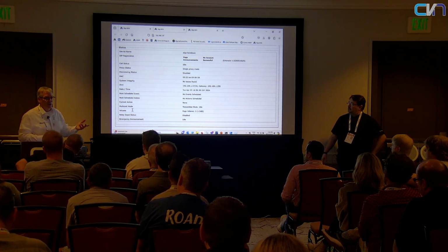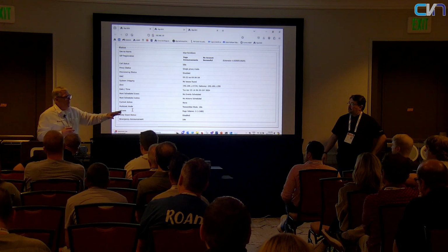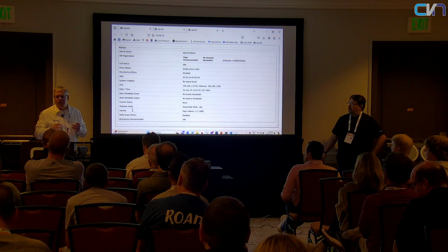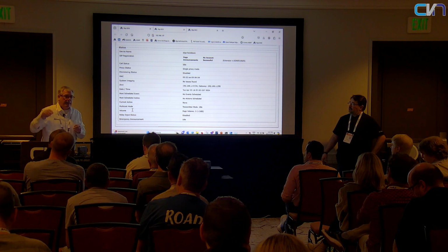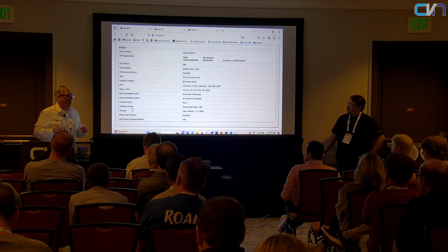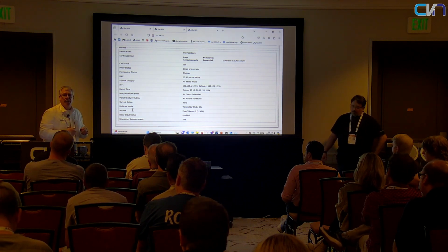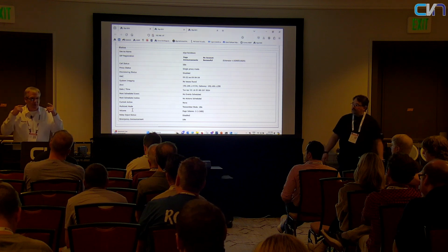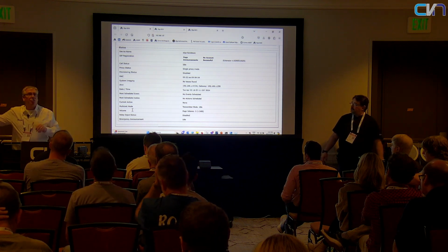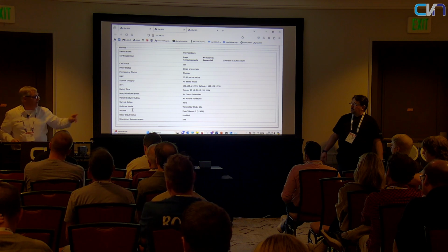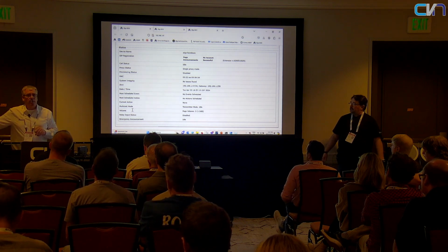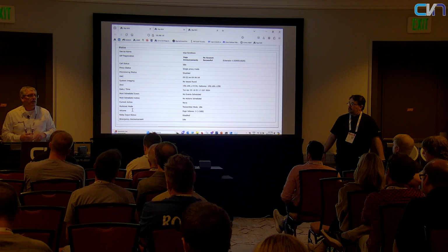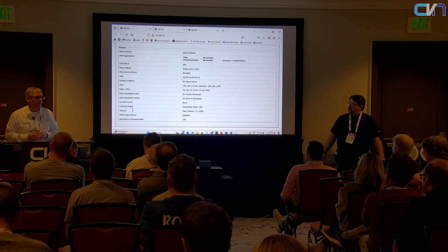When you're doing emergencies, you would typically do all your emergency broadcasts on what we call a priority channel. It doesn't matter who's paging or what's going on, we're going to override and interrupt it. There's smart logic in our accessories. If you had a volume control and we turned the volume off in the speakers in here and he triggered an emergency, it would override the mute you've done and play the emergency over the speakers. There's all kinds of logic built into the devices.